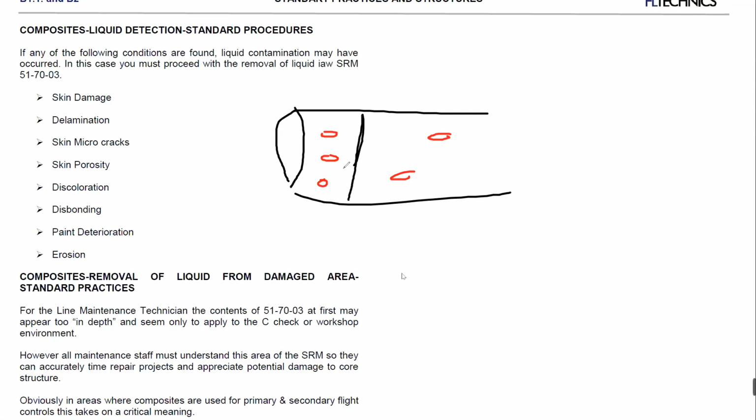So he decided to be professional and cover these spots with high-speed tape. Because he is experienced, he knows very well that when you apply high-speed tape, you have to make the corners rounded. So he made very beautiful patches from high-speed tape, and he covered all this missing paint. But he didn't report it anywhere, not even in the logbook, not even to the customer, the operator, nobody. It's a very good-looking repair, but unofficial.